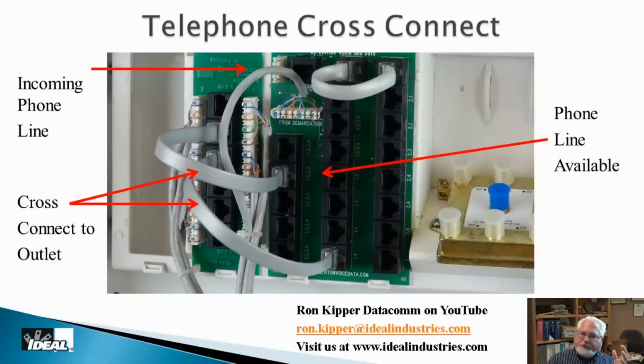Okay, the board to the left of that is actually a Category 5E rated board that feeds jacks out here at the outlets in the rooms. Okay, and this is a Category 5E jack, and that jack could be phone, could be data. In this case, I'm making them phone, and so if you can imagine, all we need to do to make this outlet in the room a phone jack is to grab some of these gray little jumper cables that one of the panels would come with.